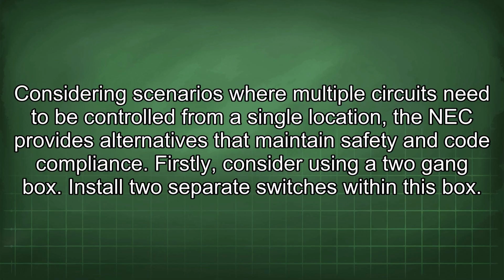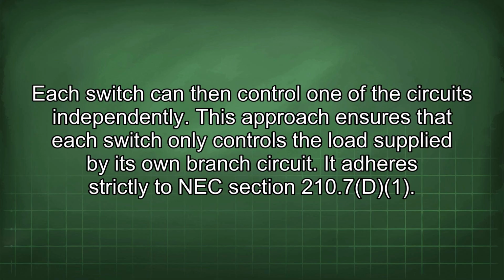Install 2 separate switches within this box. Each switch can then control one of the circuits independently. This approach ensures that each switch only controls the load supplied by its own branch circuit. It adheres strictly to NEC Section 210.7(D).